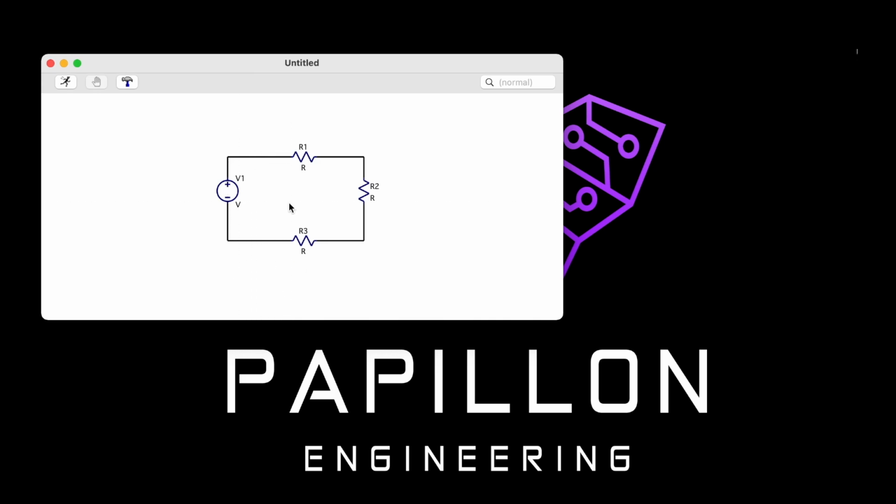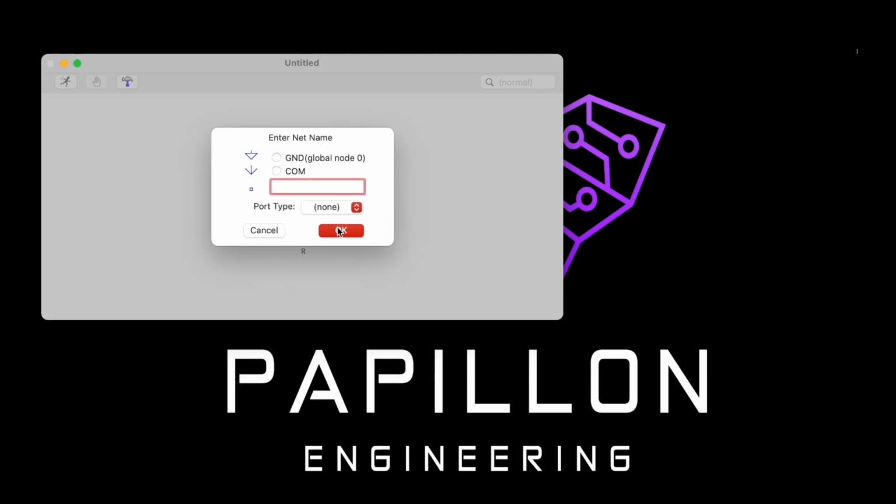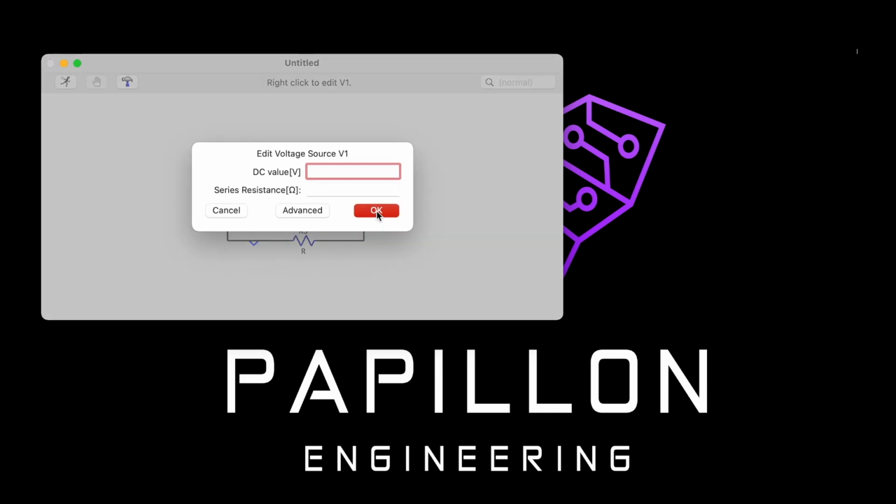All right, so once you have your wires set, you can do a couple of other things. What I like to do is go over to this net name and give it a ground. Without a ground, most simulations of circuits actually won't work. So I'm attaching a ground as close as I can to the negative terminal of my voltage source, so that way I have that universal ground component there.